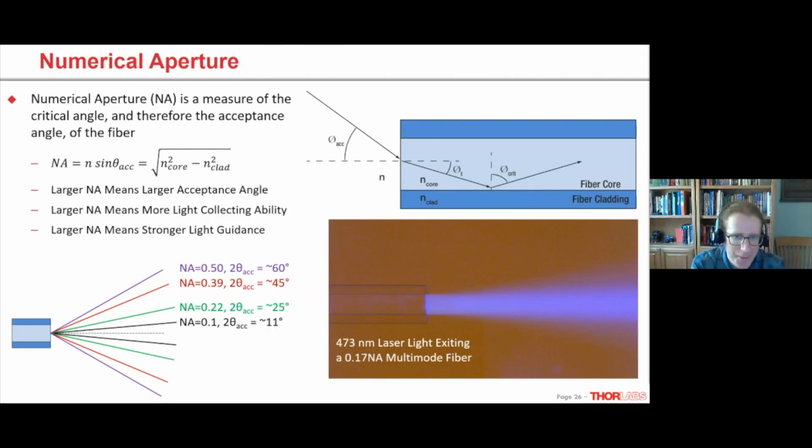So this photo, we've shown it in a few different webinars because I think it's really cool. What we did is we cleaved. This is a multimode fiber, of course. We did a flat cleave on the end, and we have this fiber under a microscope immersed in index matching oil. So that's what lets us see the fiber without the curve on the front.